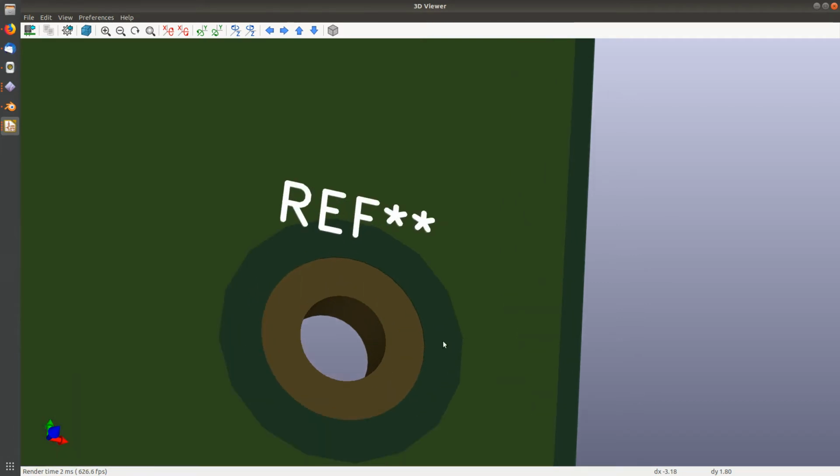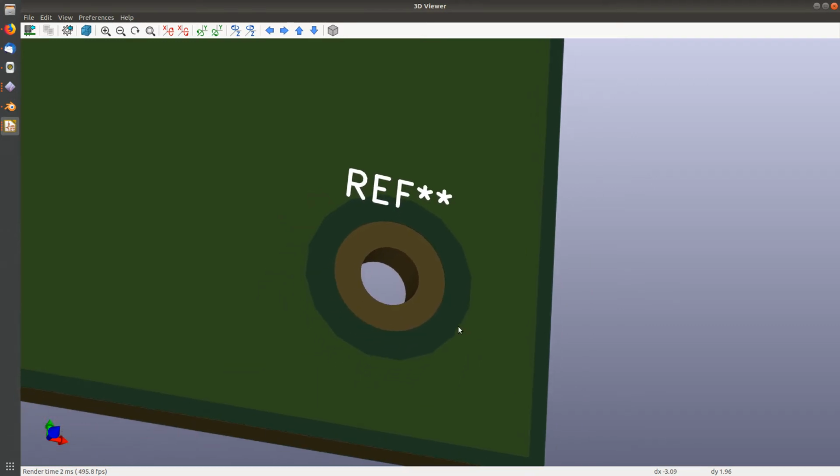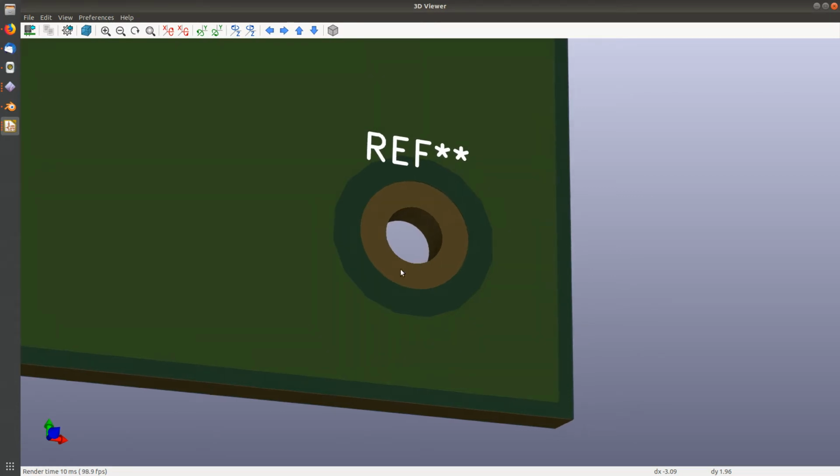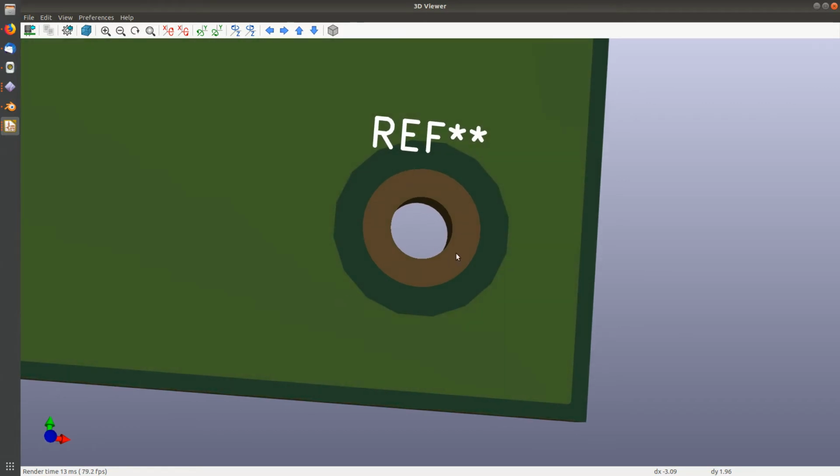So why do I want this to have an overlap like this? Well, if you end them both exactly the same, you have two potential problems. One, if your vendor can't put the solder mask in perfect alignment with the copper, and zero of them that exist can. Even if they say they can, they can't. It's just not possible. No one's perfect.